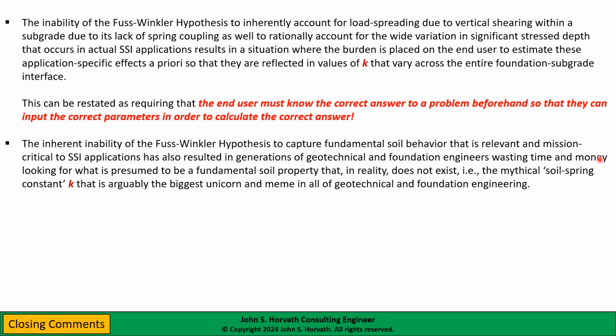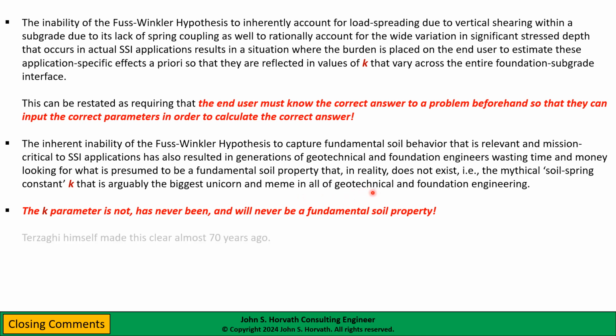Right? This mythical soil spring constant K is, in my opinion, the biggest unicorn and meme in all of geotechnical and foundation engineering. I've said it before, I can't say it enough. This K parameter is not, has never been, and will never be a fundamental soil property. And if you don't want to believe me, maybe you'll believe Terzaghi. He made this clear almost 70 years ago.